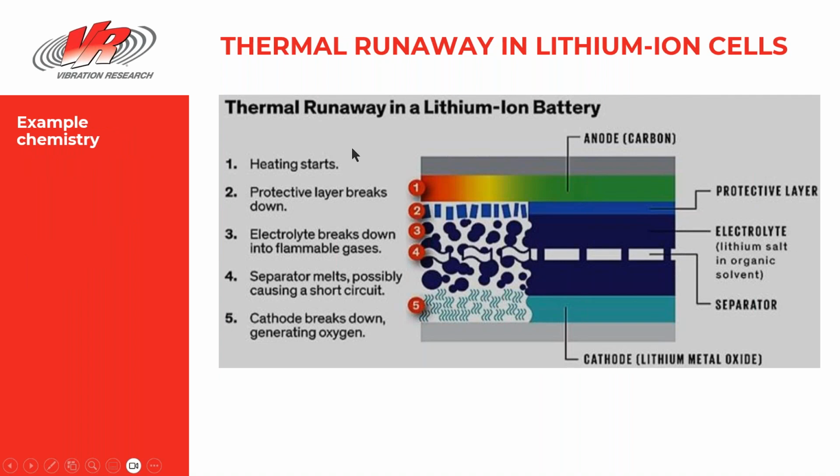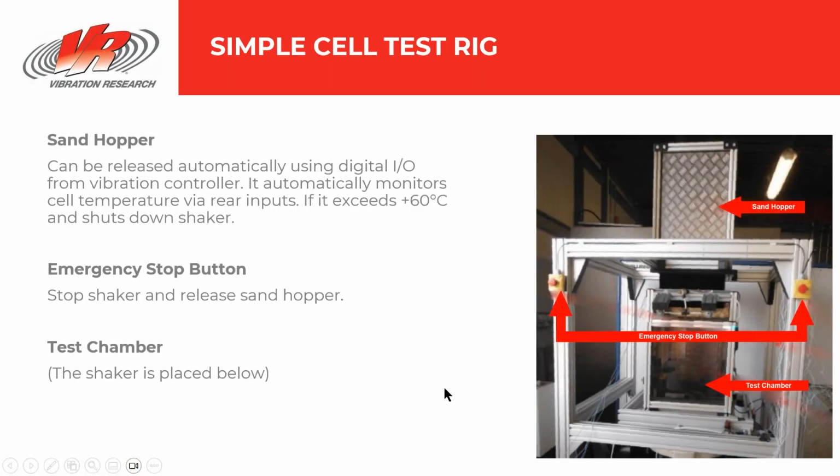I'm sure most people that deal with batteries know that you can get thermal runaway within lithium-ion battery packs. And when the cathode breaks down, it generates its own oxygen. So it's not something that's going to go out by itself, unless you reduce the heat associated with the breakdown of the cathode. Otherwise, it's just going to keep burning away. So that's the main issue of why you get thermal runaway with lithium-ion battery packs.